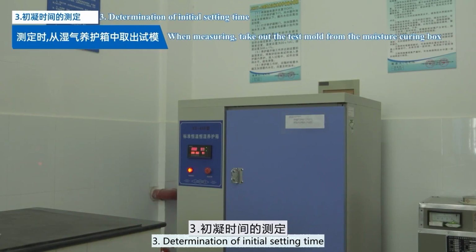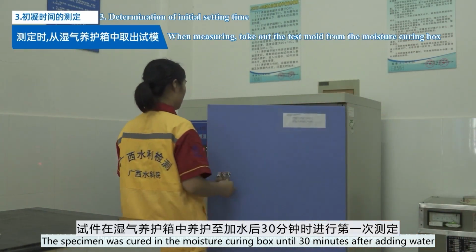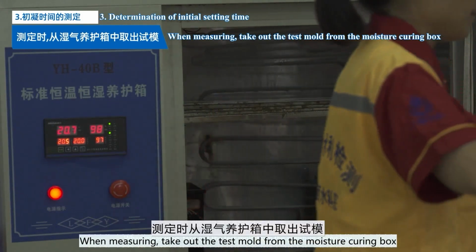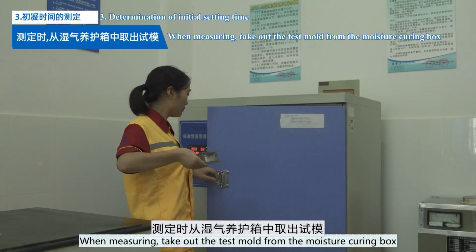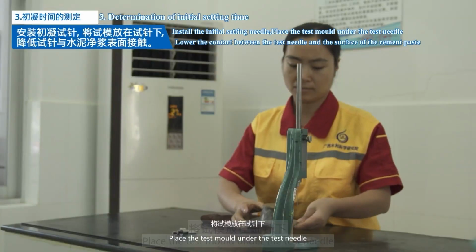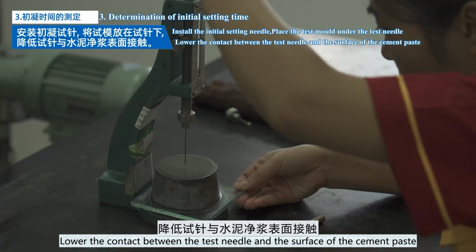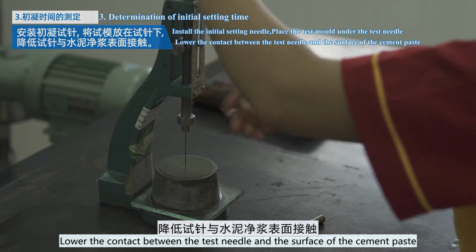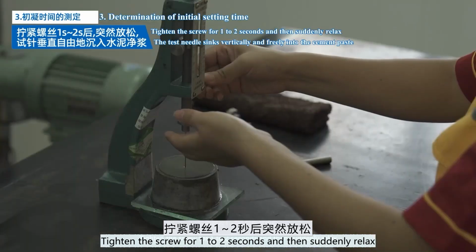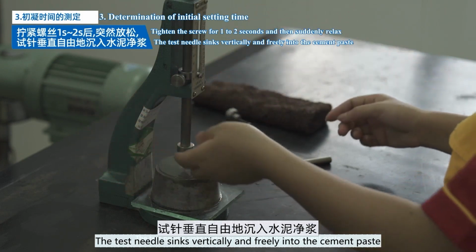3. Determination of initial setting time. The specimen was cured in the moist curing box until 30 minutes after adding water. When measuring, take out the test mold from the moist curing box, install the initial setting needle, and place the test mold under the test needle. Lower the needle until it contacts the surface of the cement paste. Tighten the screw for 1 to 2 seconds and then suddenly release. The test needle sinks vertically and freely into the cement paste.